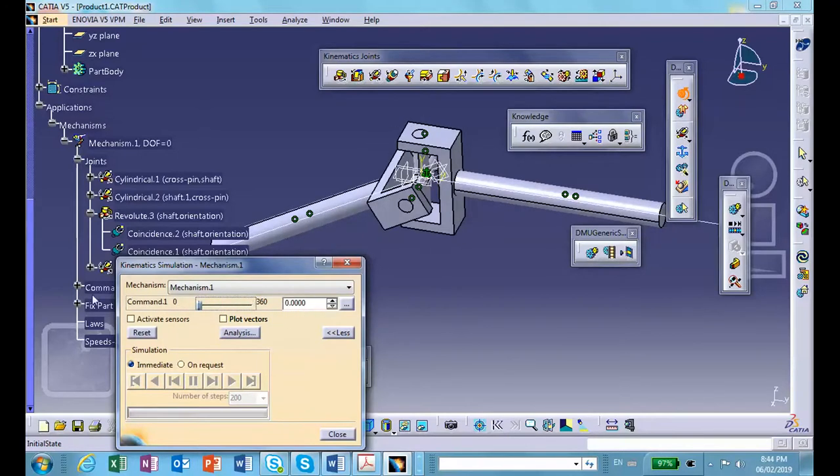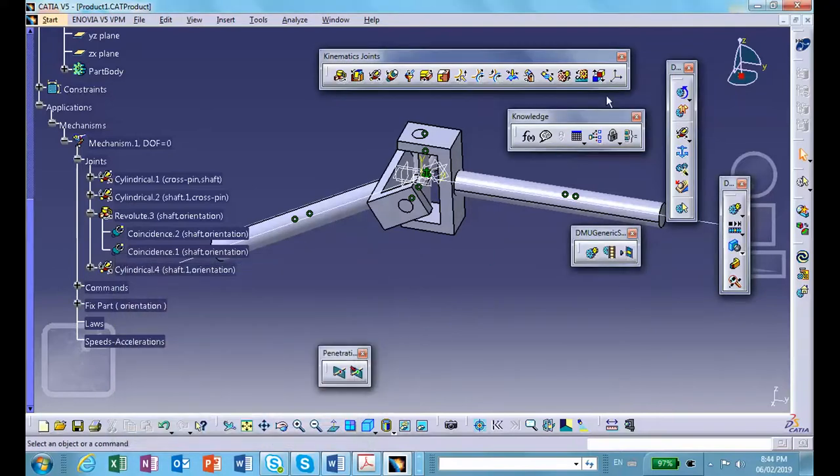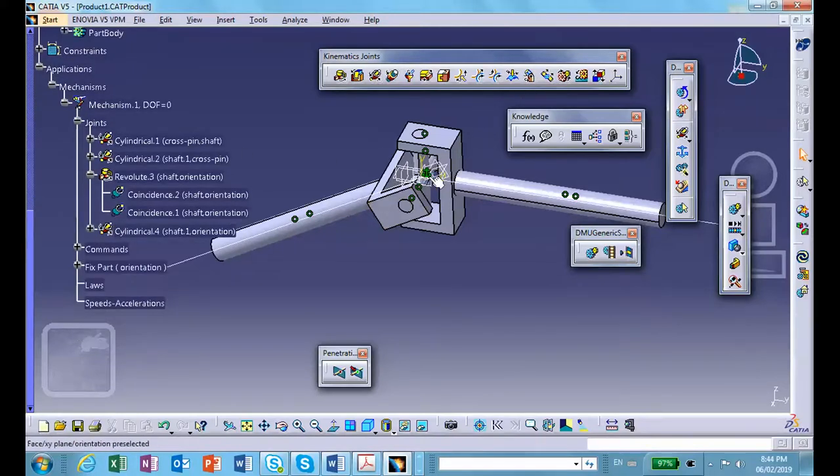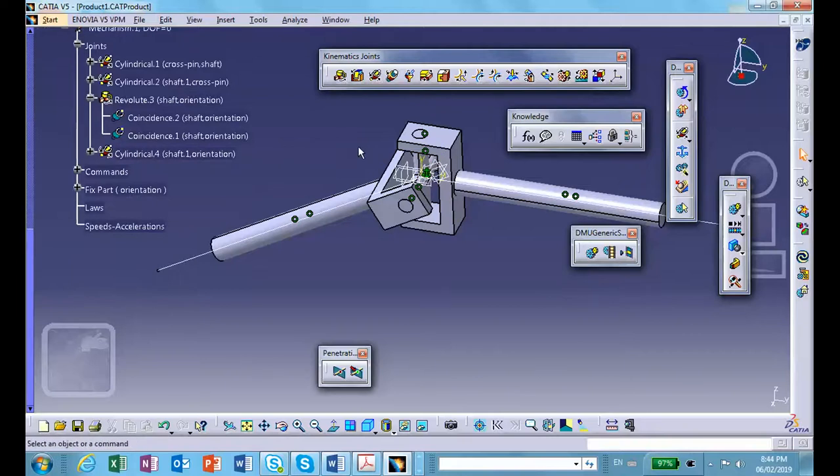And you know, this is fine. We did it, but I never actually used this universal joint that you see here, right there. Okay. This thing works. There's no problem, and I can put physics in it. But the question becomes, what is the purpose of this universal joint here? Now notice that the role of this cross pin is really secondary here, because if you want to make sure that motion is transferred from this shaft to that shaft, according to the laws of universal joint, then we really don't care about that pin.